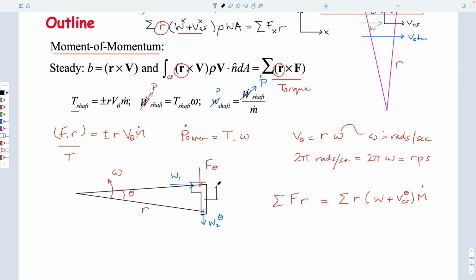It doesn't matter so much. In the same way we talked about when we started class today, you have to write the velocities of the control surface congruent with the Cartesian directions. And we chose this so-called right-hand rule of x, y, and z. The rule for rotational behavior is the hitchhiking rule, which is, this is the axis z, and this is the positive direction of rotation. It doesn't really matter so much, just so long as you do things relative to this rotational direction. So if you're looking down on this picture on the board, then z would be coming through my head, and the positive direction would be counterclockwise as we've drawn it.